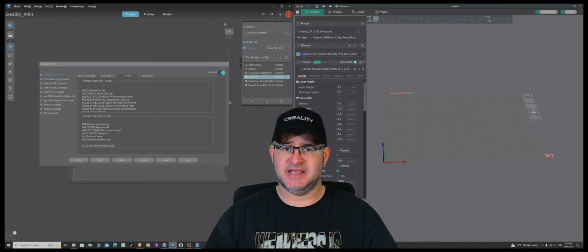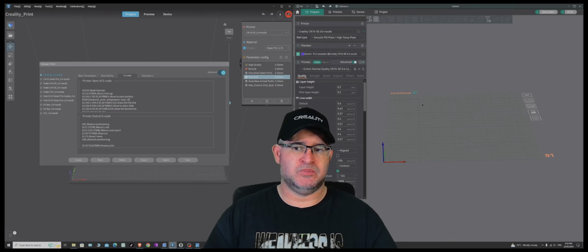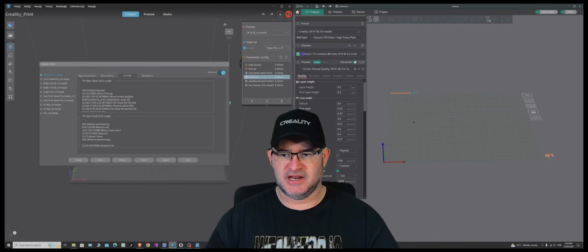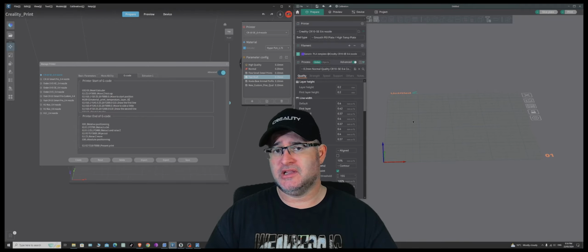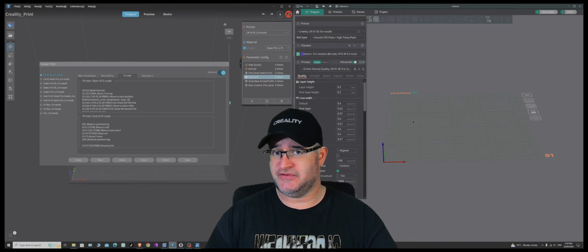from your factory, I would say factory, but your generic slicer that is mostly factory compatible with your printer. Being that the CR10 SE is with Creality, thus using Creality Print, I've got the Creality Print G-code. Now, getting back to the M109, if I was to copy that start G-code over into Orca Slicer, it will accept it, and that's no worries. But when you load your file, you configure your profile settings, you set your layer heights, and all the other settings that we'll go into later on in the next parts of the video series, you'll go to click print and it'll home Z, set the bed, and then it'll do calibrations if you select it to do so.